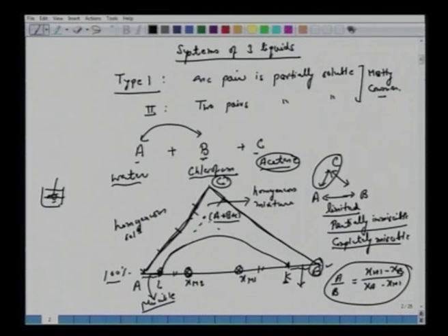So this is a phase diagram we have got like this. For the ternary system A, B and C, we have a homogeneous solution mixture in this range. If you hatch it like this, and if we now choose a component or a mixture here of A plus B plus C within this region and allow them to stir, you will see a separation like this. There will be two phases. One phase will contain the amount given by these coordinates, another phase will contain the weight fraction of C given by this coordinate.